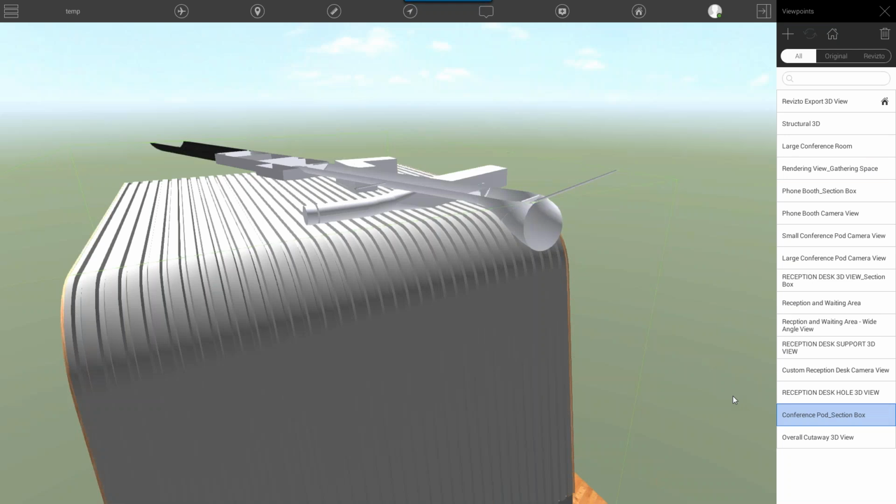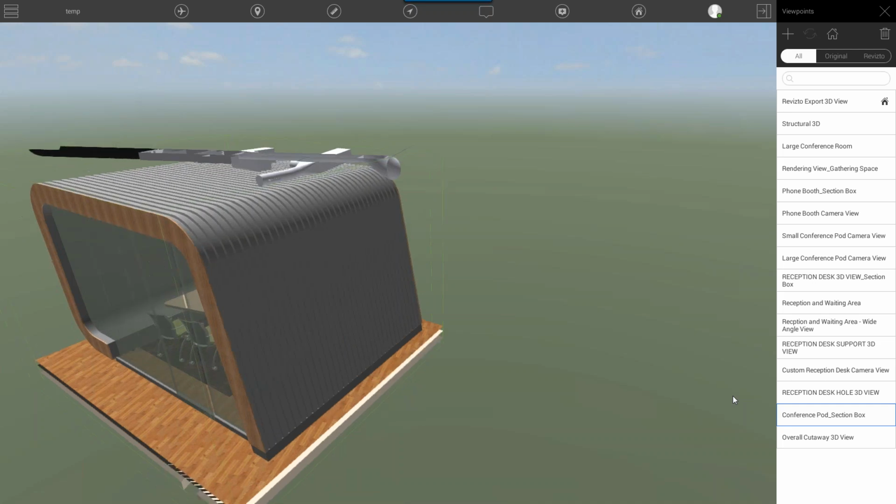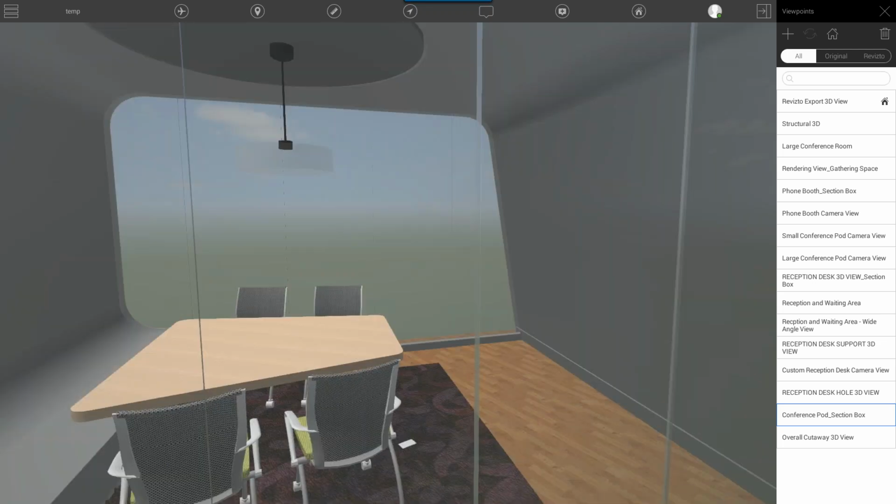And so everything I've done so far, I've used the mouse with my right hand. I'm right-handed. And then with my left hand now, I'm starting to use the 3D mouse. And so I find this to be the most efficient way to move around in the viewer, because you can move this in multiple directions at one time. Whereas if you're using the Revit or SketchUp type navigation, it's a little bit more limiting, or if you're using the gaming mode as well. So within this view here, I can look down and see the carpet that was defined within one of the design options.